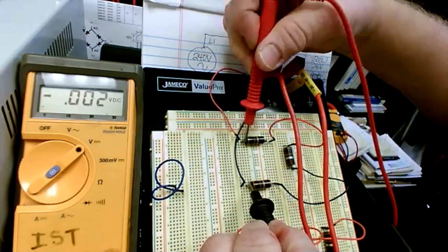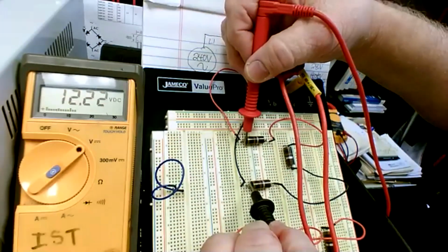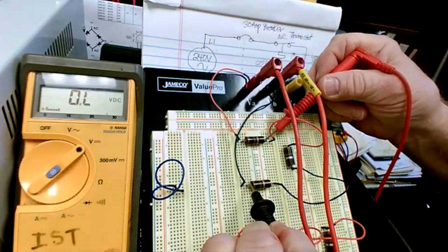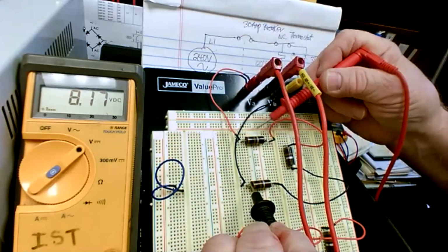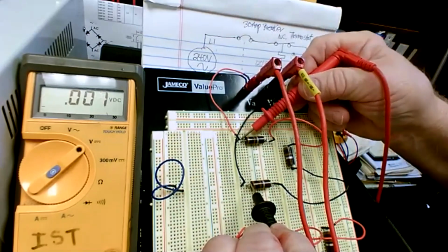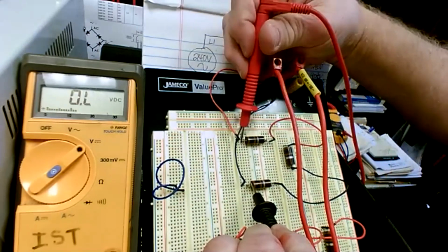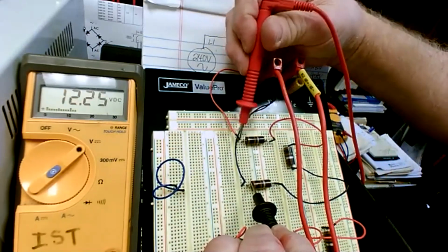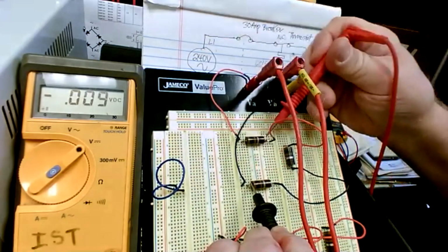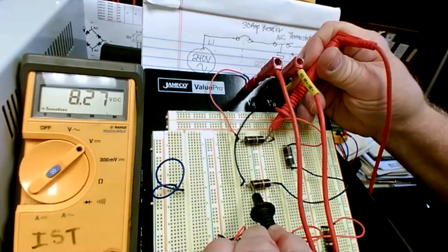If I go back, look at what happens here, guys. Look, I've got 12 volts there, 12.22. Now when I leave this one, it's actually 8 volts because I dropped 4 there. When we say we dropped in voltage, it's dropping from 12 right here. It starts out at 12, and if I leave my common at the end of the circuit and move over one place, it shows me I've dropped it by 4 volts. Now I've got 8 volts left.